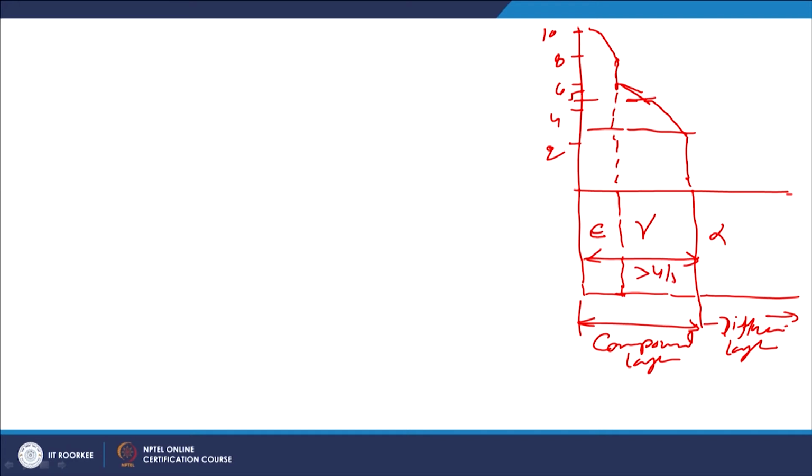which is greater than 4 or 5% of nitrogen, and below that we will have the low nitrogen content, where nitrogen is in the diffused state in the ferrite. So, this zone corresponds to the very high nitrogen concentration, then the second zone somewhat lower nitrogen concentration, and then the further lower nitrogen concentration zone is this alpha, where iron nitride is formed.